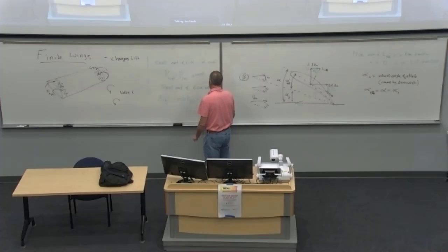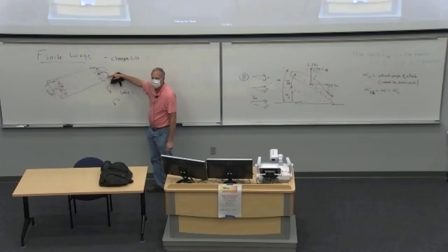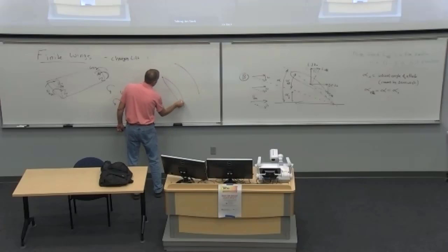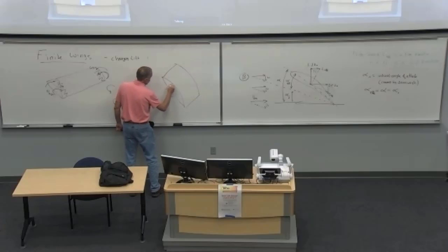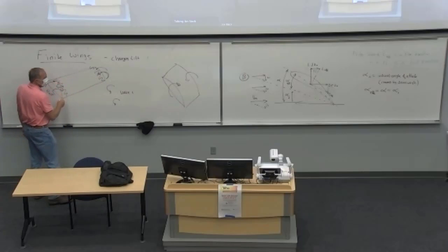So big lift, big pressure difference, big downwash. So the formulas are going to reflect that. And then the other deal is that if the wing is long and thin, then less of the wing gets affected by the downwash, because the downwash is only at the wingtips. So if you have a real short, stubby wing that looks like this, the downwash affects most of the wing. Whereas if you have a long, thin wing like this, the downwash only affects part of the wing.